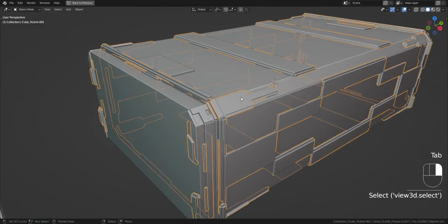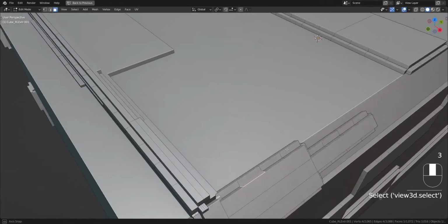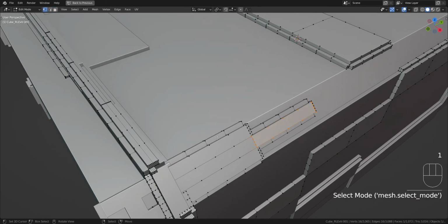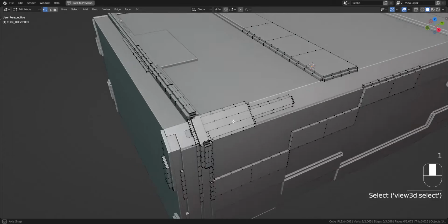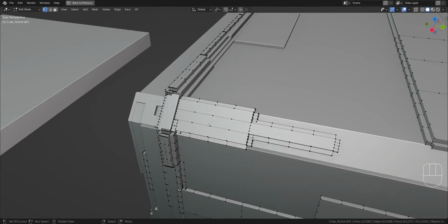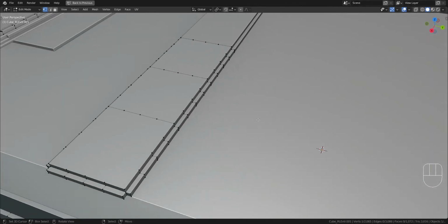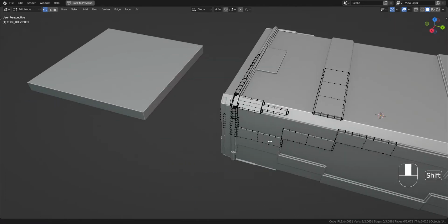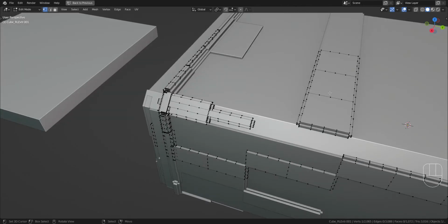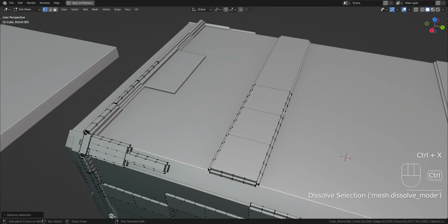You can see here, most of the quads are on the side, but on the top are a bunch of ngons. And this is what we have with limited dissolve off. So it's kind of filled with a bunch of useless verts that is better removed than of course kept.